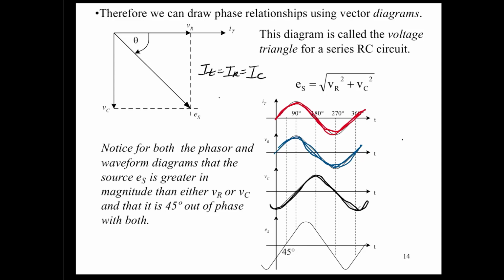And I think I mentioned this before, instead of using sine waves to prove values in an AC circuit, we simplify that by showing each one of these sine waves as a phasor and show phasor addition to give you your total value, and it just simplifies things greatly. But even if we look at these values in the time domain, you can see that as far as the I total and the VR value, they're in phase. There's a 0 degree phase shift